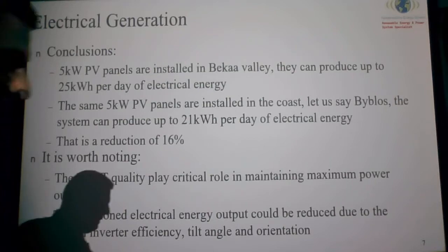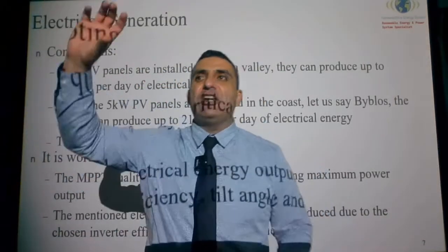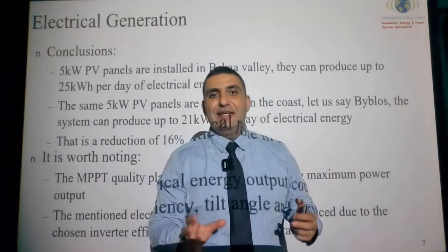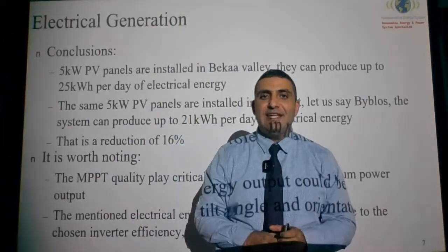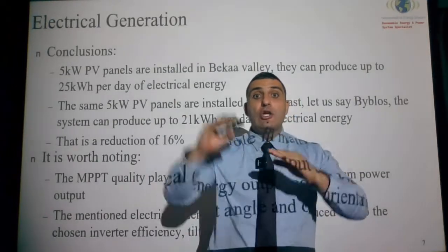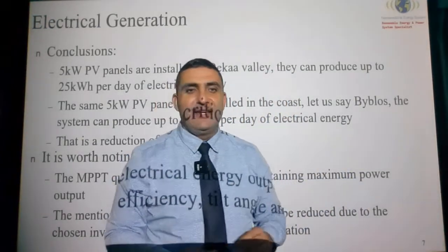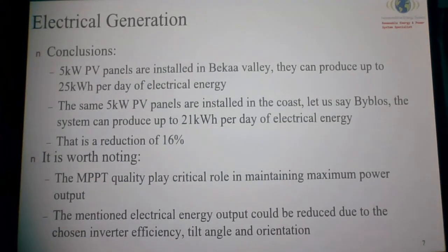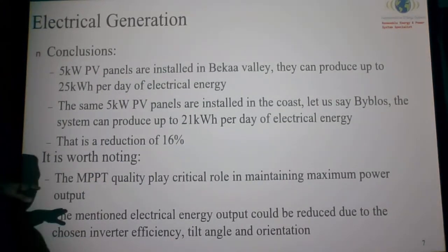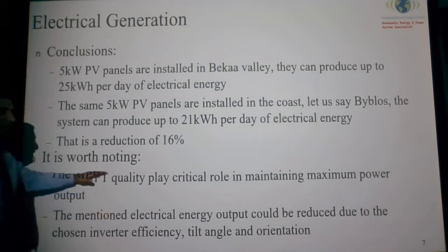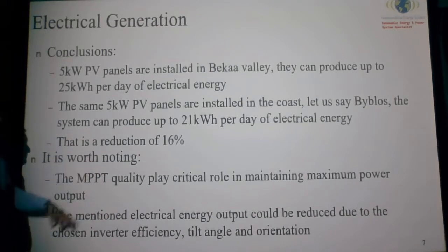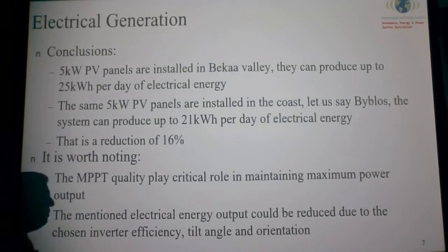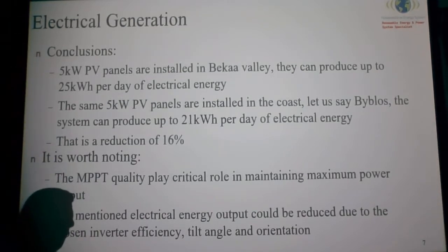These days, some people use a separate charge controller and then they use an inverter separately. This system has a different efficiency if you go ahead and use an all-in-one system, that has MPPT and your inverter and a UPS and APS, whichever you have in your system. So your chosen equipment efficiency will drop the system down further.